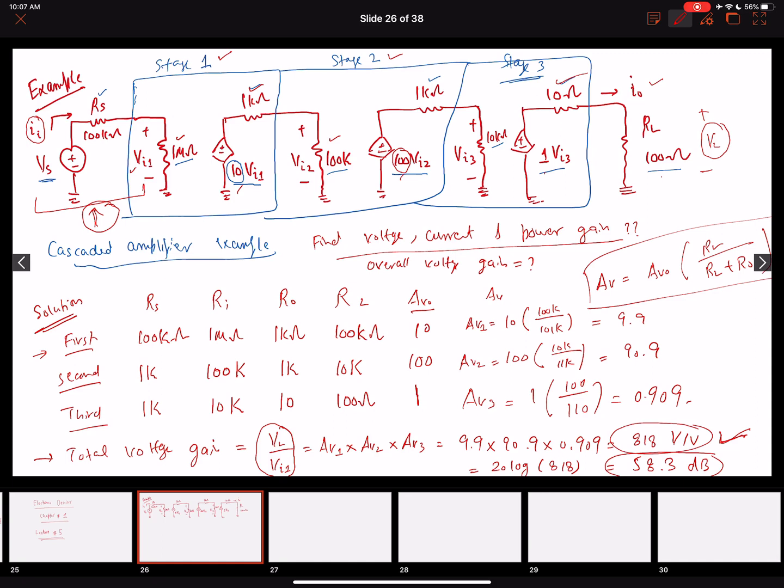So we discussed the design considerations in the last lecture. If you remember, we want a very high input impedance and a very low output impedance for a voltage amplifier. We will discuss other types of amplifiers in this lecture as well, and you will realize that the design conditions for a good current amplifier, transimpedance or transconductance amplifier may be different. For a voltage amplifier, the input impedance should be very high, ideally infinite, and the output impedance should be very low, ideally 0.